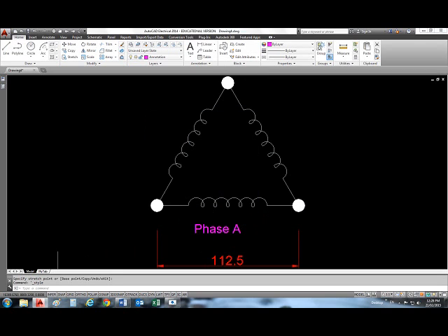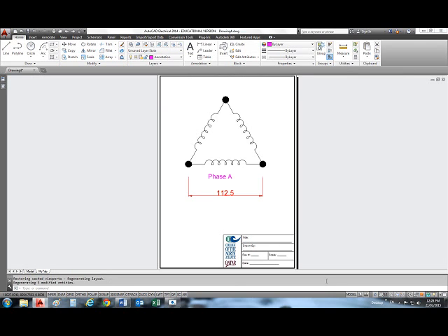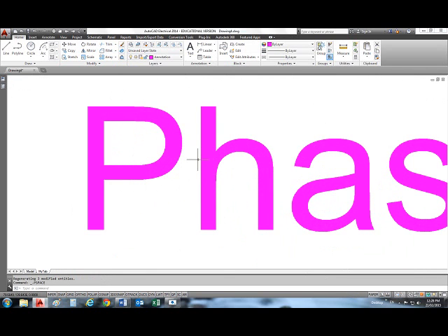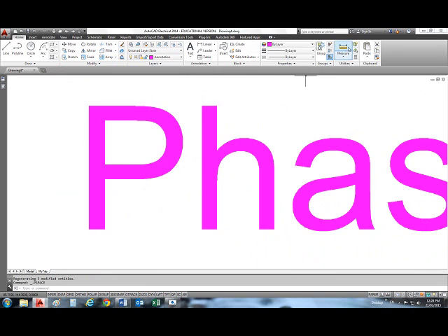Okay, and if you're in doubt, you always can go to paper space and zoom in and then measure. So from here to there, and you can see that it is exactly 7.00. It'll be plus or minus a few fractions, but very close to 7 because we don't have snap points on paper space.